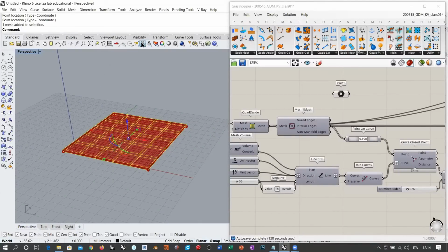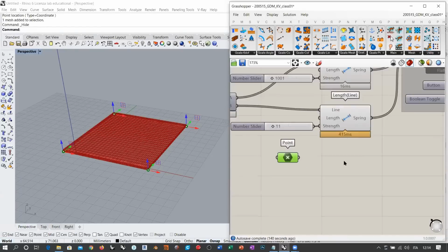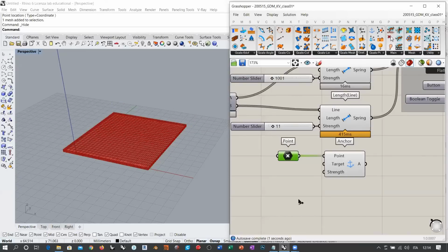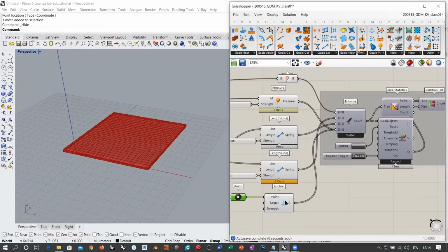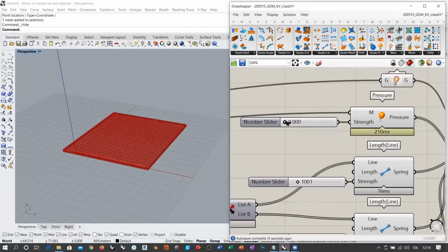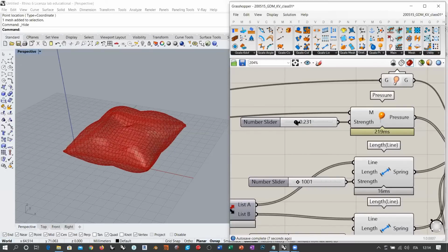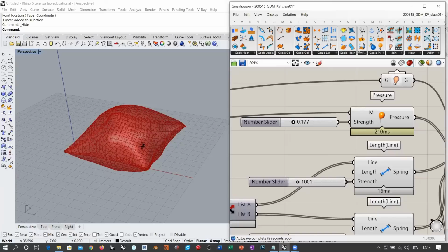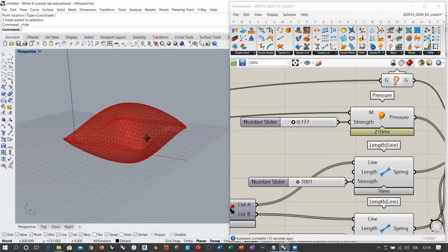Okay, so I'm going to hide this mesh again, and I'm going to anchor my mesh using just these 4 points here. Non-geometrical preview, so it can go together with pressure. I don't care about it. And run this simulation again by increasing the value of pressure. Now I have 4 anchor points, so those points cannot move. So this object is forced to stay horizontal, okay? It can still expand vertically, okay, freely.